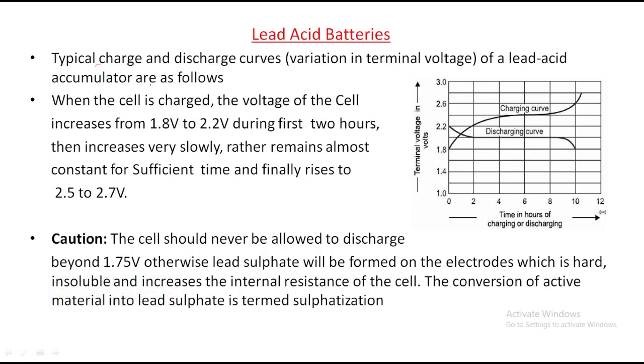Charging means, a simple point you have to understand: with no charging, the terminal voltage will be 1.8 volts. The terminal voltage of the battery will increase from 1.8 volts to 2.7 volts, and in order to increase this it will take almost 10 hours. This lead acid battery will take 10 hours, right?